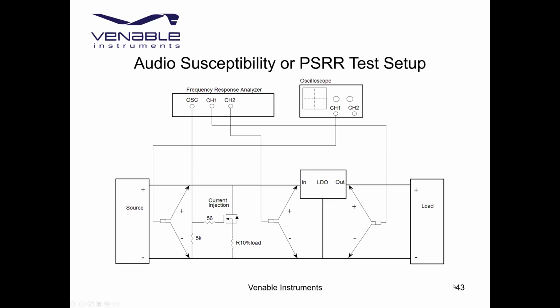They just call it audio susceptibility when it's a switching power supply, but it's the same principle. And then when you get to MIL-STD-461, CS101, I think is what they call that particular section of that test. The test runs from like 30 hertz to 150 kilohertz. When you're injecting into the load, I believe they want you to calibrate how much power you're putting in, which I believe is now 80 watts into a half ohm resistor.